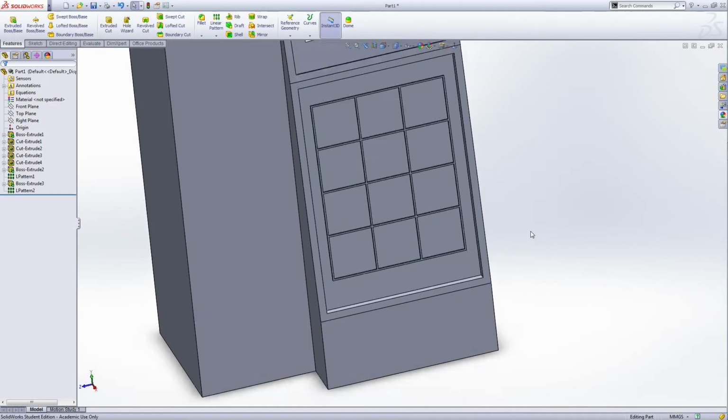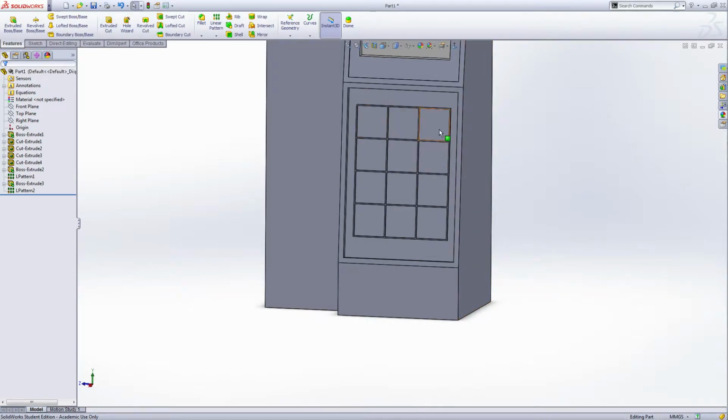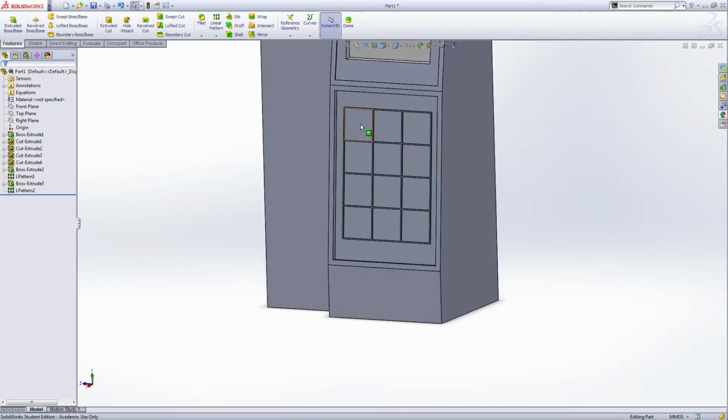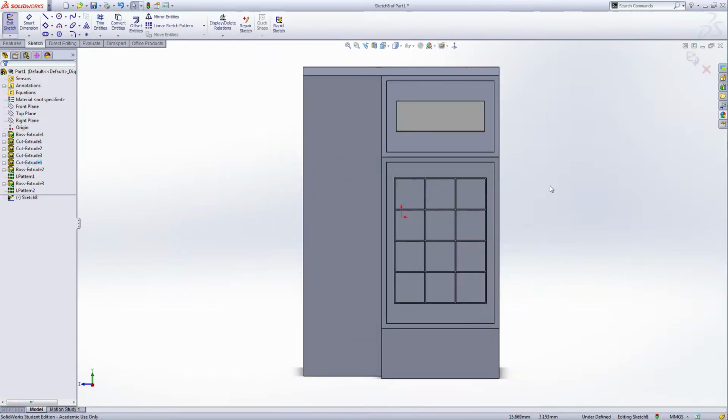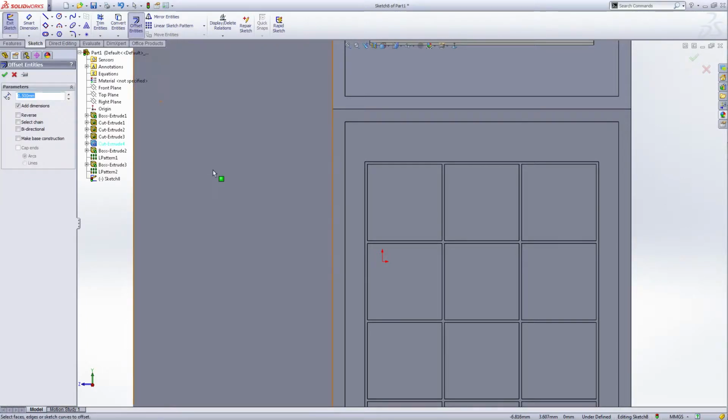Okay. Now get the frame for the keys, frame for all these number keys, and now we make the number keys. So click the inside face and then make a extrude base. Okay. Now we make the offset. Still use the offset entity, and this time the distance of this keys is 0.1.